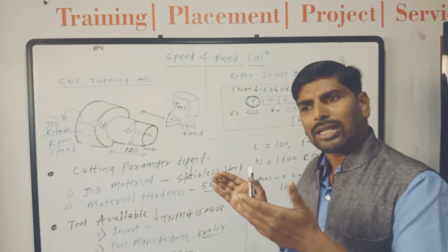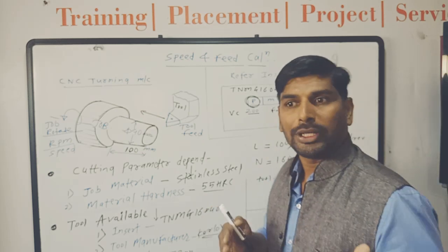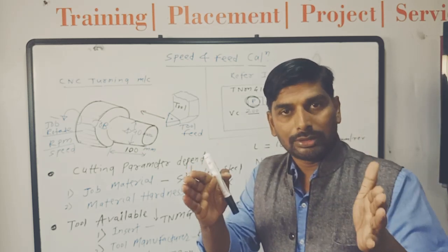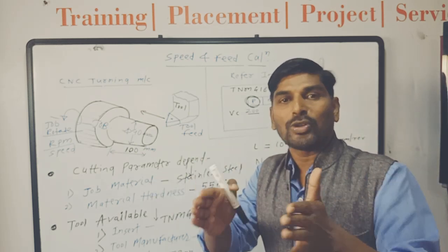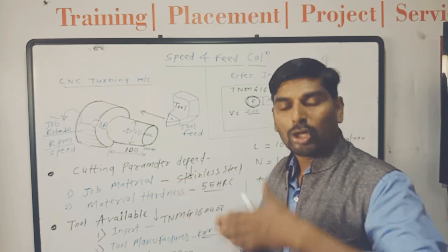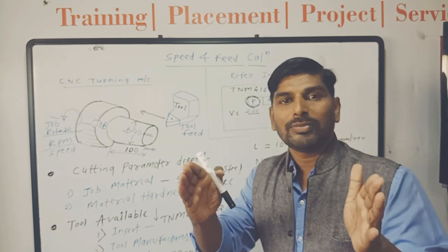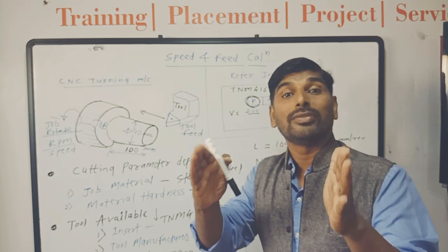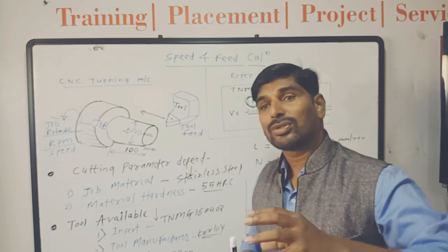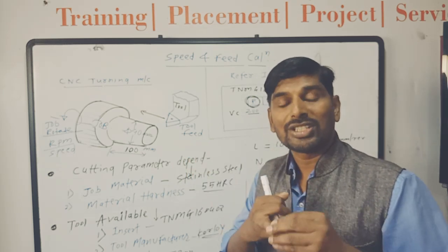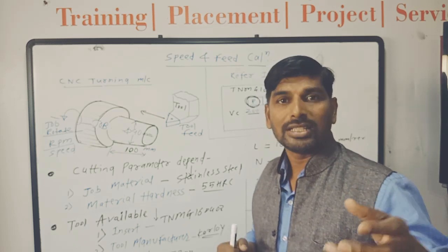Like that, there are so many things. Again, fatigue of the operator. If you are working 8 hours a day, it is not possible to count 8-hour production. Normal industry considers an 8-hour shift as only 7 hours of production. So that is called rest time, lunch time, human fatigue, that needs to be added.